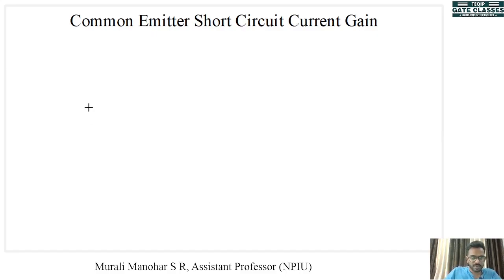Now we can draw the circuit. Here is our Vs. I am directly going into the equivalent circuit model. There is the Rs, and here we will have RB, either just RB, a single resistance, or the combination of R1 and R2, which is R1 parallel R2. So this is RB. Here we will have our model.